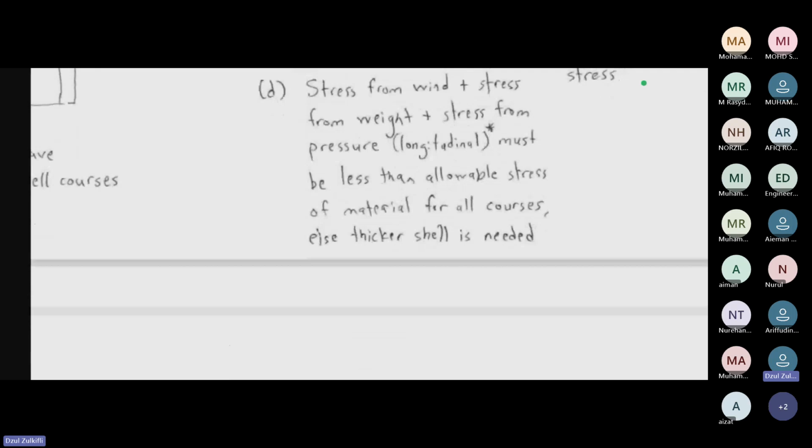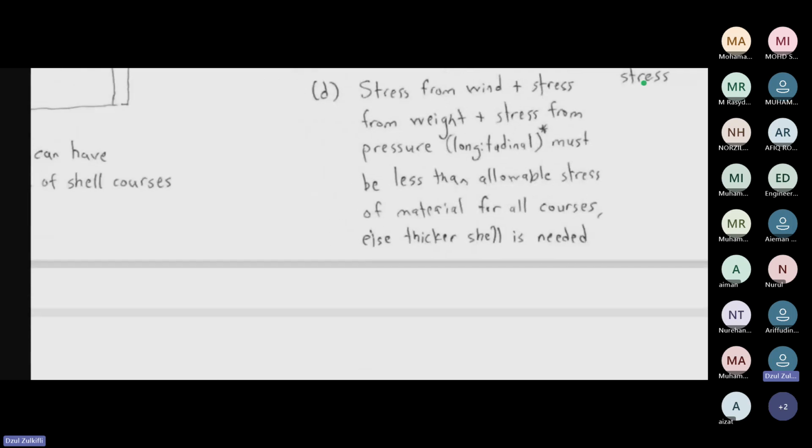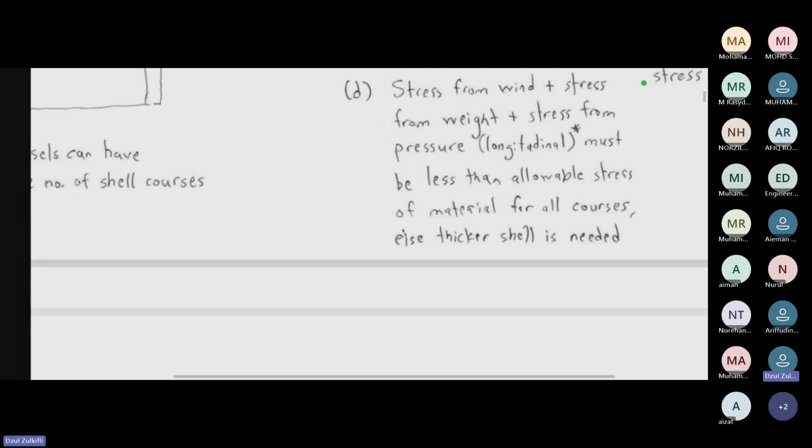So I'll give you an example. For example, a tall tower, right? The internal pressure is low, so maybe 3 mm is the required thickness after doing the P equals PR over SE formula. The external pressure is also not so high, right? So maybe around 5 mm for example. But because the location is a high wind area and the shell is located slightly at the bottom area, then the stress becomes very high. It could be 7 mm needed due to wind. Then 7 mm should be your benchmark for Tmin. And if you reach 7 mm, you need to do FFS.